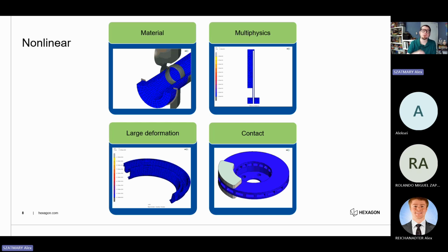And I hope you can see that many of these techniques are also relevant to Formula SAE. Still, a lot of the critical finite element applications for formula, let me see what comes to mind. One is, of course, looking at individual parts and making sure that they have good dimensions so that they're not going to fail, make sure that they're going to be strong enough under the loads that you predict. One of the structural analysis tasks that is particular to vehicle dynamics is making sure that the torsional rigidity of the vehicle is stiff to keep the tires on the road in the way that you desire.